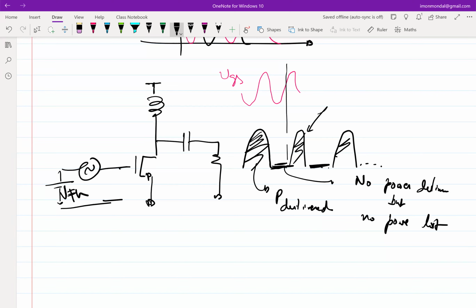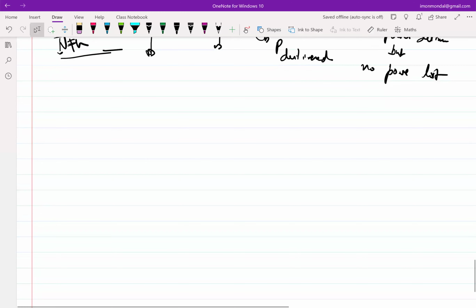But obviously you see a problem, there is cutoff and all those things that happen, right? So we'll have a lot of distortion because of this. So the alternate thing to do is to say that if I use a differential circuit, right? I should not say differential, I should say another replica of this, which operates on the negative half cycle. Then I can add those two currents up to get the full cycle. Correct? So how do I do that? So I have this one, this one.